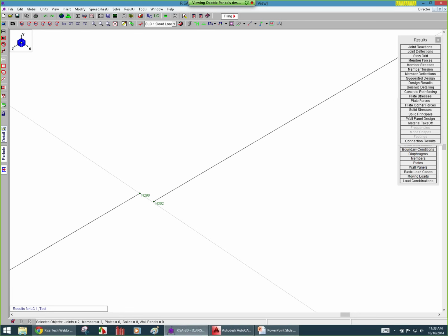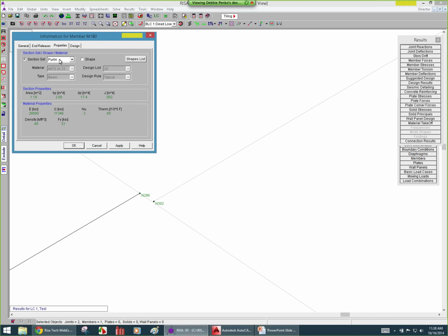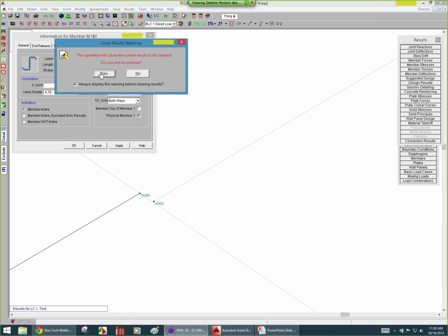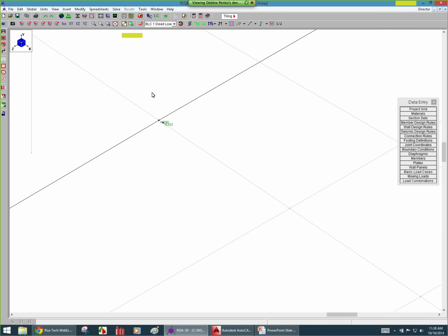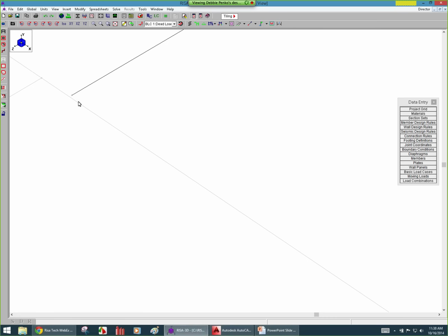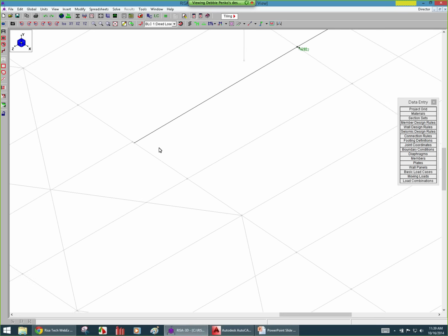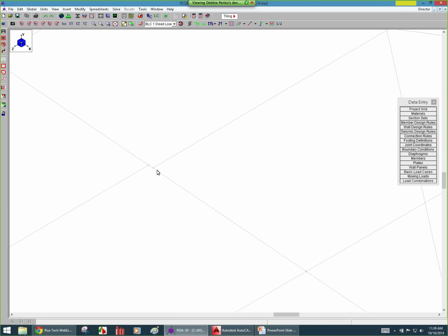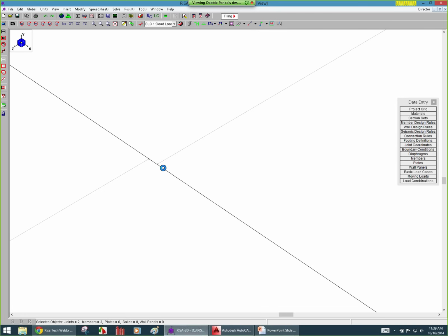So this purlin now goes to 290 instead of going over to the 302. So we'll say it goes to 290, and it will break the solution and it pops it over there. Now, hopefully that's my only problem. It looks like I have a couple that are not quite attached there. So I might have an issue with these purlins, it looks like I just had a small modeling error as I go around.